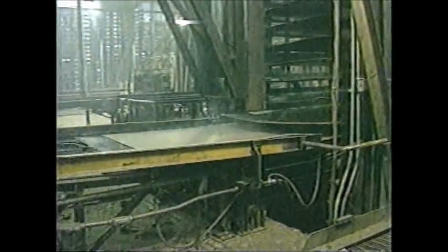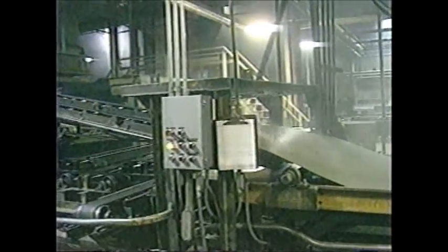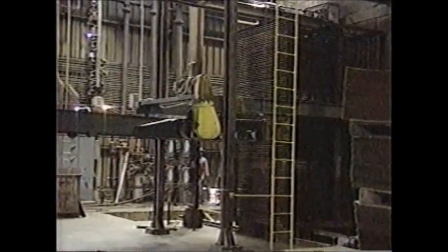The pressed boards are separated from the cauls and sent through a series of cooling fans. After cooling, the newly pressed boards are stacked prior to conditioning. In the conditioning process, a rack of boards is sent through a tunnel or kiln and is subjected to heat and humidity to bring the moisture content of the panels to between 5 and 6%. This ensures the panels will be dimensionally stable in use. The panels then leave the conditioning tunnel to be unloaded from the rack and to be graded.